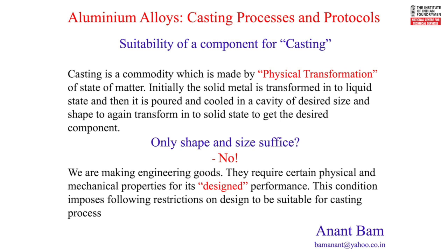Thickness adequacy, fluidity. The liquid metal, as it advances ahead in the mold cavity, starts losing heat to the mold walls and to the air within. This heat loss makes the viscosity of metal rise progressively. Metal becomes sluggish and eventually stops moving. Since it is an inherent property, it forms a limitation on the casting wall thickness and span, or the length of the run, how long the metal can flow.